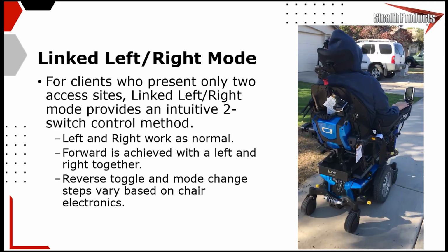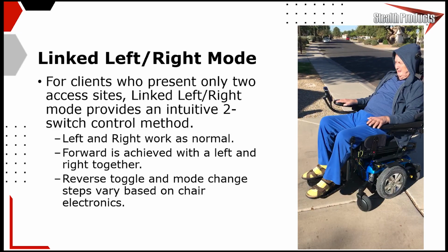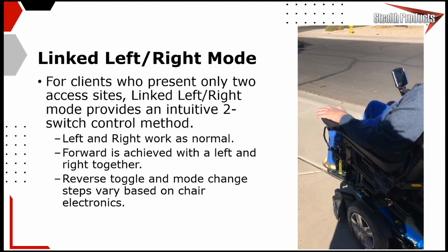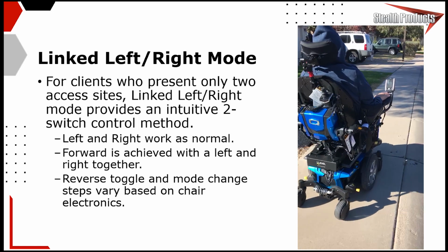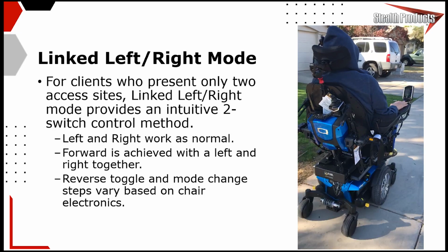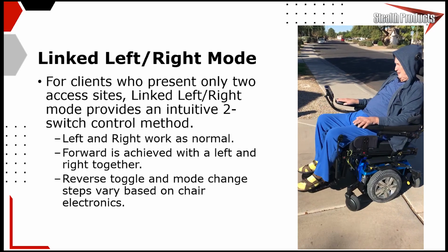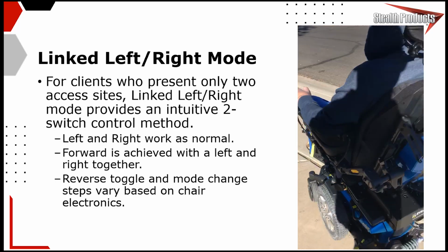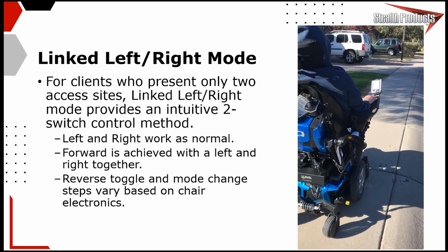But like this particular setup, it works great for drive control for like bulbar onset ALS, where those guys lose their upper extremity mobility pretty early, but they're still walking and have decent leg control for a while. So this same method could be fiber optics at the end of the arm pads if needed. There's a lot of different ways we can use linked left-right mode. And now we can toggle into reverse using this, just like you would a head array. You can change modes with that, but these same two switches would control all of that, but how we do that is a little dependent on the chair.